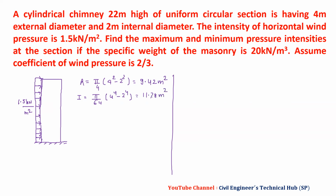Then we have P, which is the weight of the chimney, and that is equal to unit weight of the material into area into length. That is gamma into volume. So this is given 20 into 9.42 into 22. And we have this weight equal to 4144.8 kilonewtons.